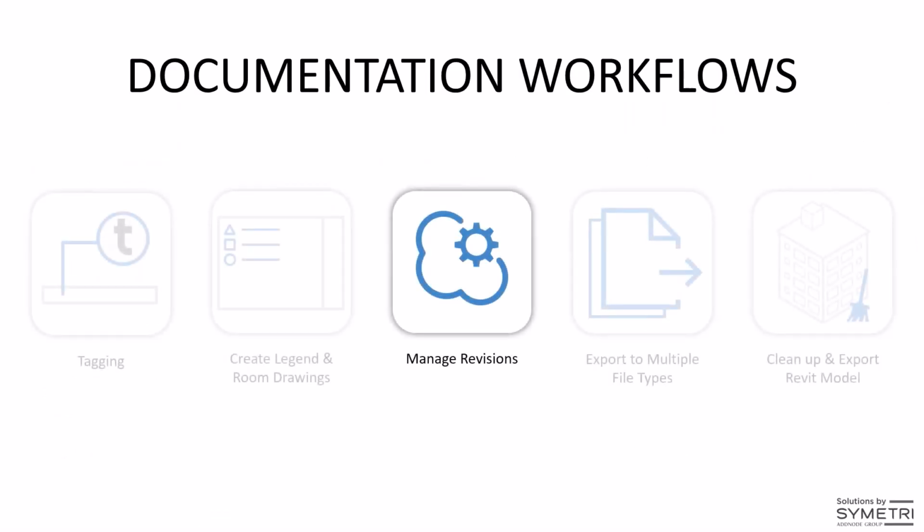So we created our sheets, we tagged them. Now let's look at how to manage your revisions. Now in Revit, only in 2023, we are able to add revisions to multiple sheets at a time, but with the Revision Manager, we're able to do that and so much more. From being able to filter to find sheets, to selecting sheets easily and modifying revisions or adding revisions and removing revisions, to creating print sets of revised sheets, and also the ability to utilize Excel to make it faster and easier to modify your revisions.